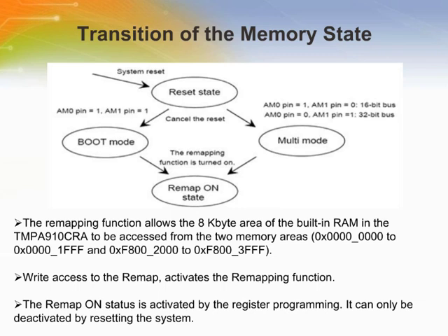The TMPA910CRA has 2 operation modes, external memory mode and internal boot ROM mode. Either mode is selected in accordance with the AM1 and AM0 pin statuses.